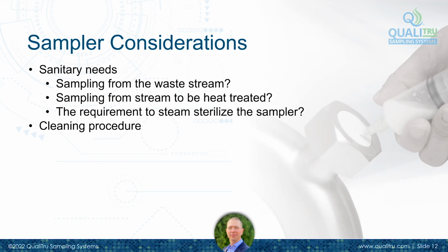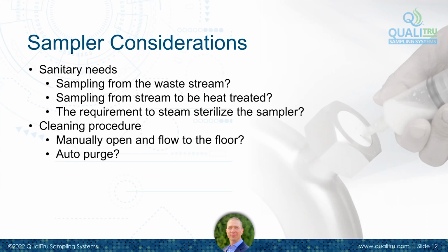We have to think about the cleaning procedure for your sampler. Is it something that can flow to the floor? Is it something that you can have moisture collected on the floor? Or does it need to be 100% retained? Do we need to build in an auto purge and have a control system? And is there the expectation that an operator will come in on a late shift during cleaning and take this apart and put it back together?